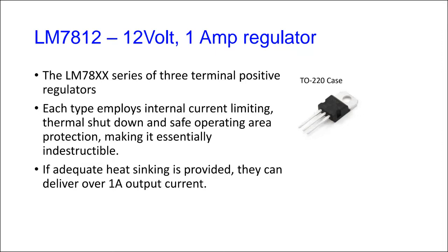If it gets too hot, so for instance, if for some reason you forgot to put it on a proper heat sink, it has a temperature sensor inside that will cause it to shut down. Right? It has a short circuit protection that will prevent it from overheating and shutting down as well. So essentially, for most practical purposes, it is indestructible. It's the kind of thing that they make power supplies for labs and for students, as we were joking about yesterday. And provided you heat sink it adequately, they can deliver over 1 amp. It will deliver over the 1 amp output current at the 12 volts. If you don't, it will overheat itself and shut down without damaging.